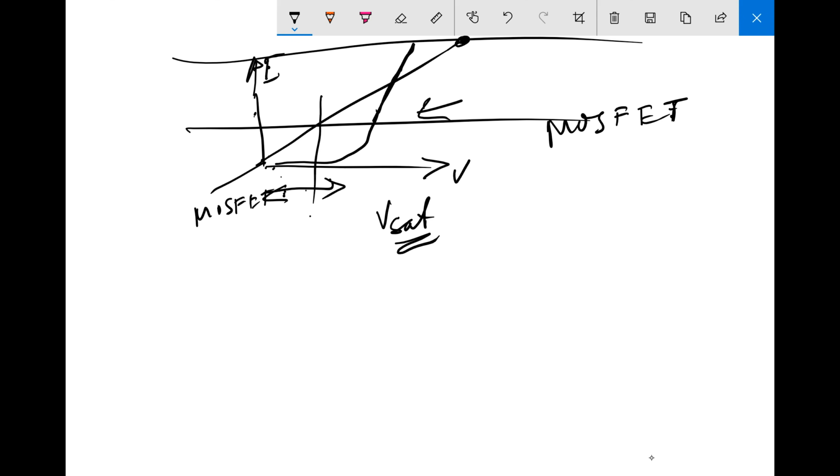And this is why IGBTs are preferred in very high current situations, like, I'd say, motor drives, where you might have very heavy current. I'm talking about hundreds of amps, okay? Because then the dissipation will be fairly low.